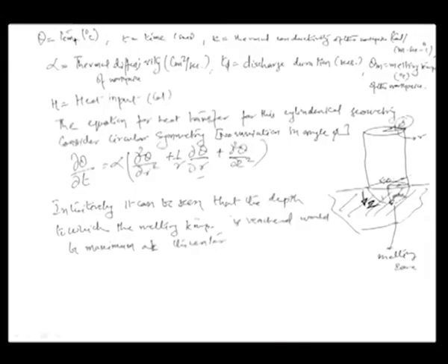So our interest principally lies in this region corresponding to r equal to 0, because this gives you the maximum depth up to which the melting zone reaches, thus giving you an estimate of the crater volume that you are able to remove using that maximum depth and using a circular diameter of a equal to 2r on the surface of the workpiece.